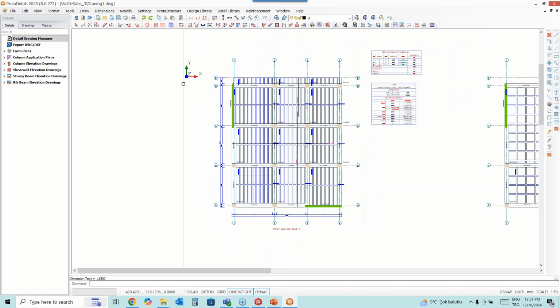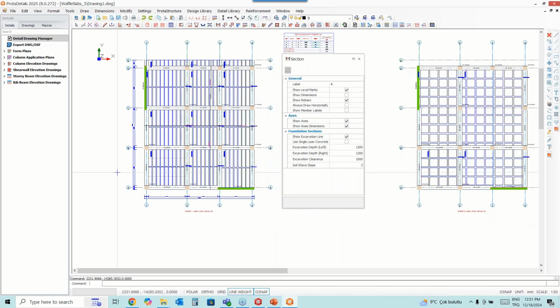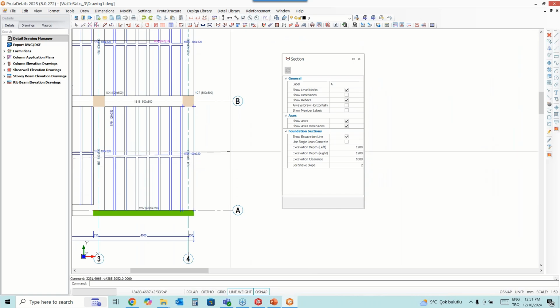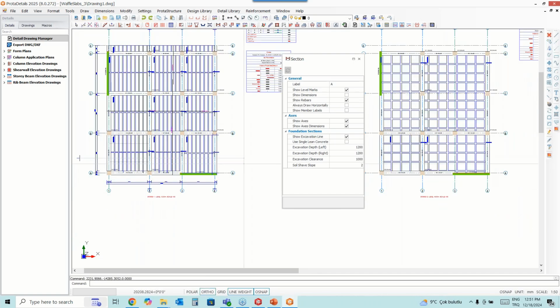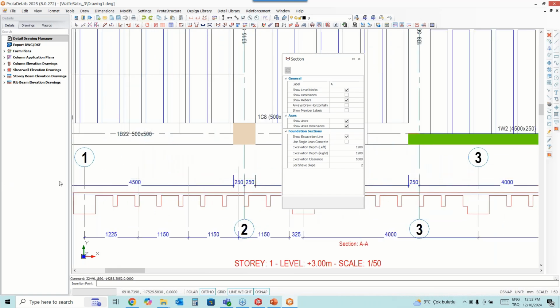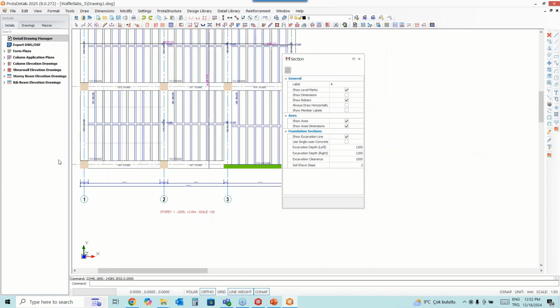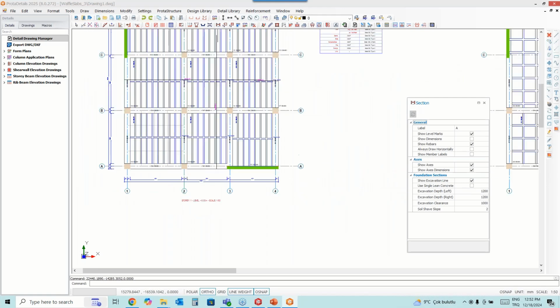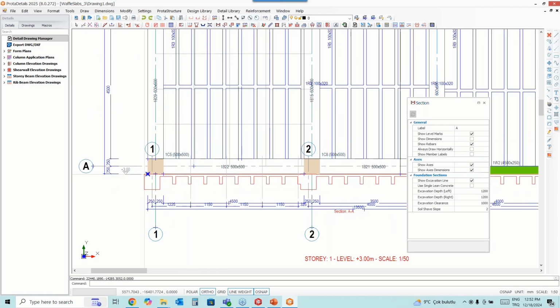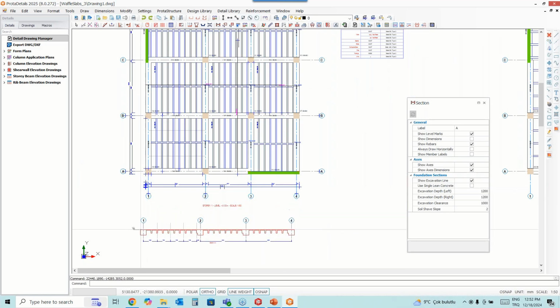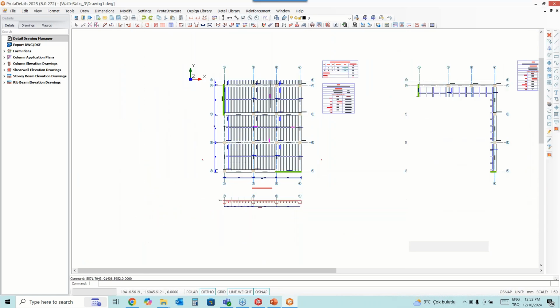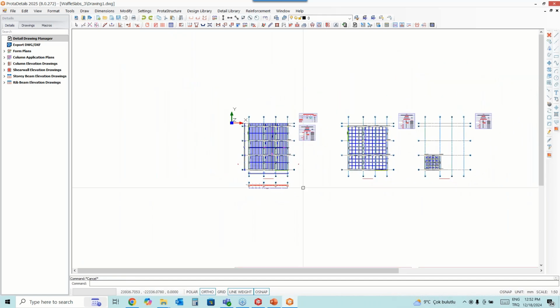You can also add a form section, for example, even so we know that there's a rib slab, so we can activate the ortho mode with F8, okay, and we can simply place this. Just I'm gonna change this position in here. Okay, so we can simply place this section like this.